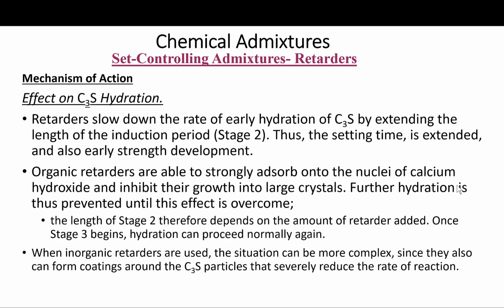The organic retarders are able to strongly adsorb on the nuclei of the calcium hydroxide, and by that they inhibit their growth into larger crystals. Further hydration is then prevented until this effect is overcome.